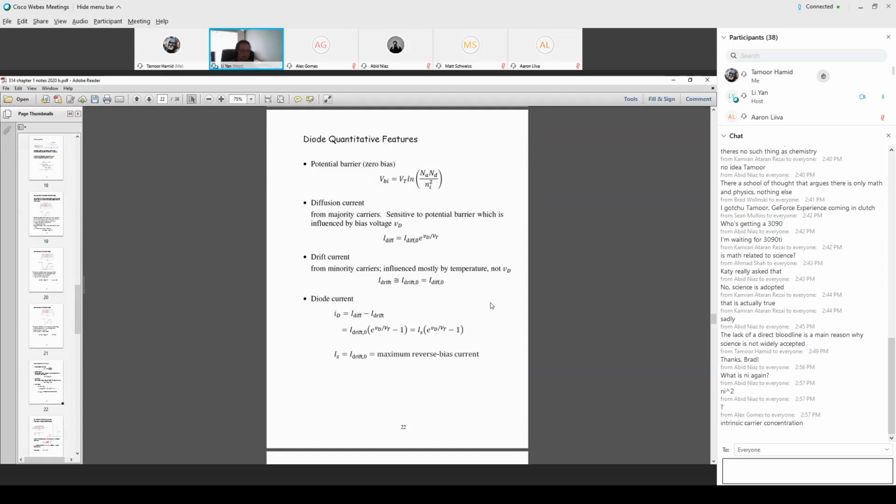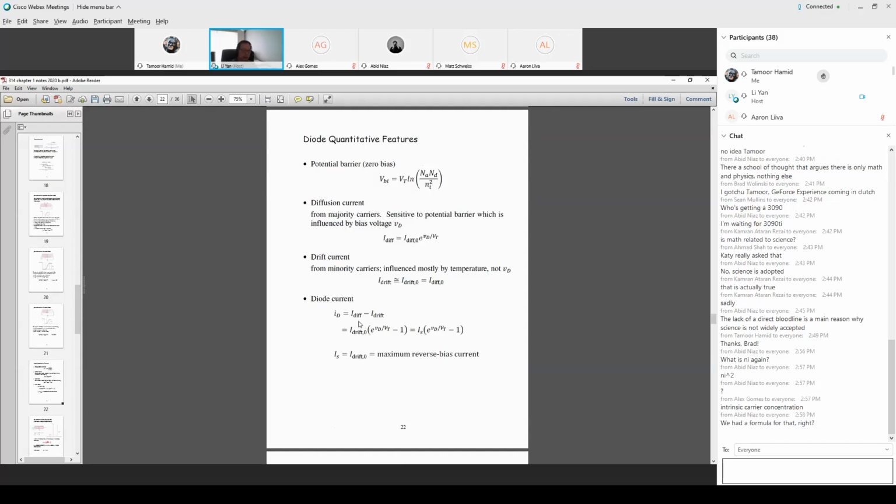Any question? So, more specifically and mathematically, how do we describe what happens in the PN junction? Overall diode current, ID equals I diffusion, substitute I drift. You substitute the I diffusion in this expression, you substitute I drift in this expression, and you can simplify into this final form. So we have quickly, in a semi-wavy way, derived the current and voltage relationship in this formula. Finally, I sub S is really just renaming this factor.